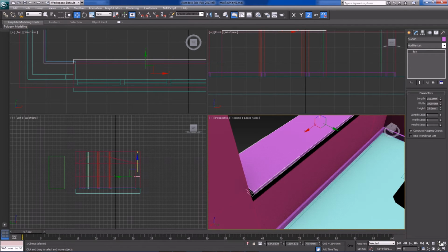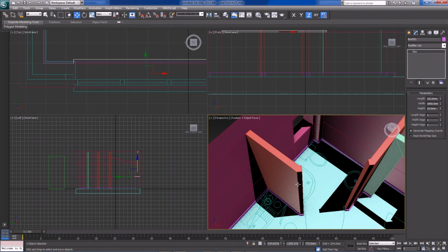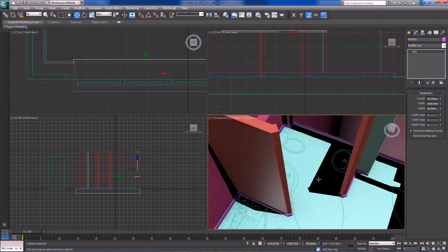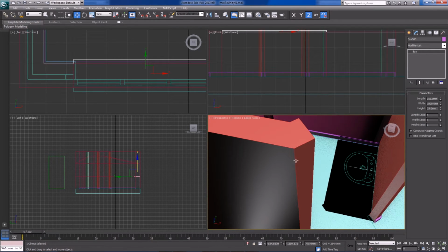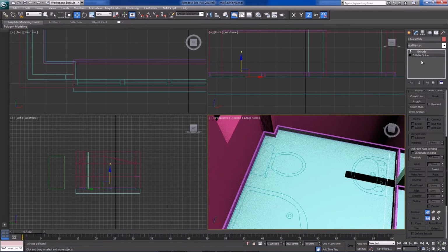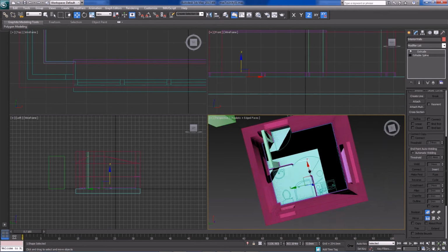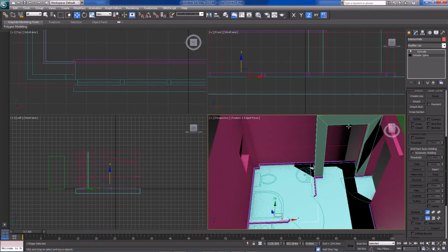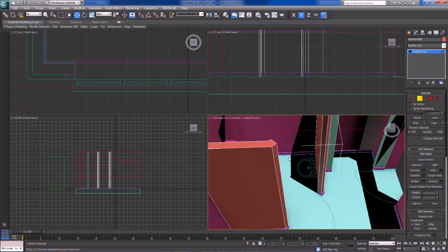We can further refine this just by chamfering it. Especially when doing renderings, I would always recommend chamfering the edges. So chamfering means you take one hard edge and it splits it into 2, 3, 4, however much you want, and it relaxes it at the same time. So it gives you a softer edge. Sometimes you can use chamfer just to create 2 hard edges. It depends on what effect you want to achieve.